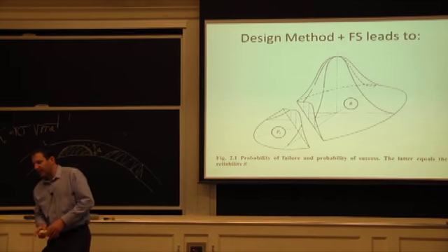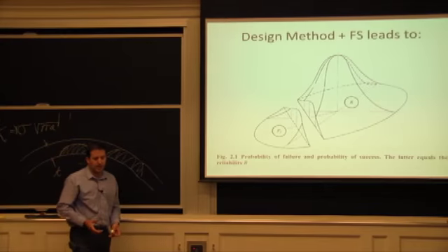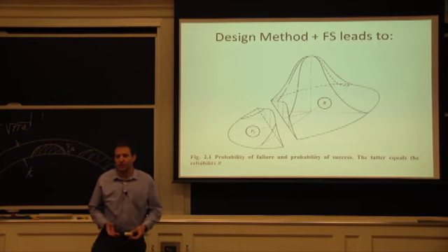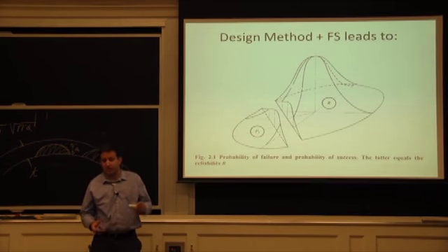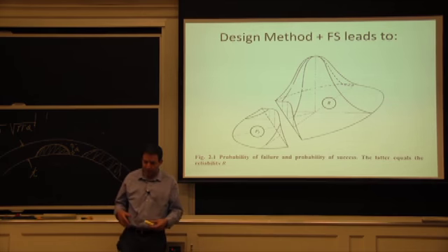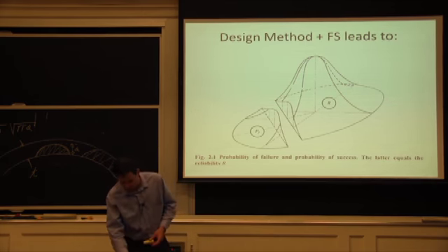This is more or less saying, and I think it's probably fair, that you can break just about anything. Everything that's being built and is being sold can be broken, one way or another. Sometimes because that specific one was not exactly as strong as the others. Sometimes it's because you just put too much load on it. So that concept is almost universal. And what we're going to go through is see how exactly after the fact we can determine that probability of failure.